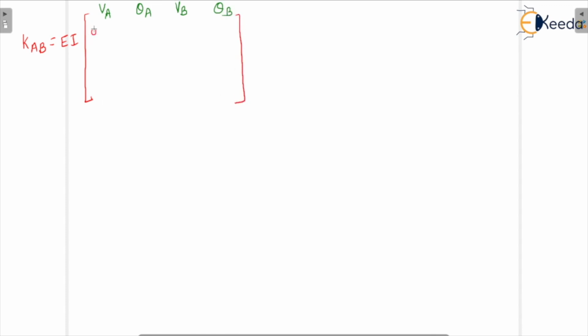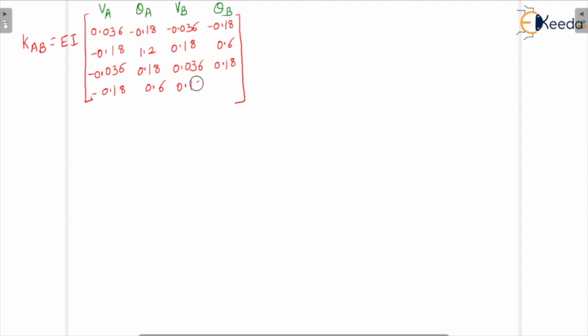Okay, so I am getting this first row as 0.036, minus 0.18, minus 0.036, minus 0.18; minus 0.18, 1.2, 0.18, 0.6; minus 0.036, 0.18, 0.036, 0.18; minus 0.18, 0.6, 0.18, 1.2. Okay, so this is corresponding to VA, theta A, VB, theta B. So this is our answer for K of AB.